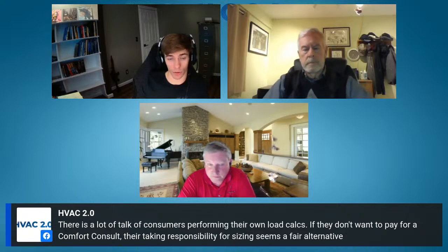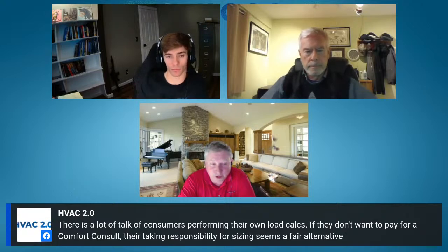Yeah. What you could do is plot it out on the likely load range. Okay, here's your likely load range. Your load calc falls here, wherever that may be. How do you feel about that? I'm making a lot of assumptions that this is correct. If we size to this and it's not correct, you're not going to be mad at me, are you? Having that type of discussion. Would you like to do a static pressure test, a duct pressure test? Your ductwork says that your equipment should be this size. Likely load range says it should be this size, and your load calculation says something totally different. What size do you want?